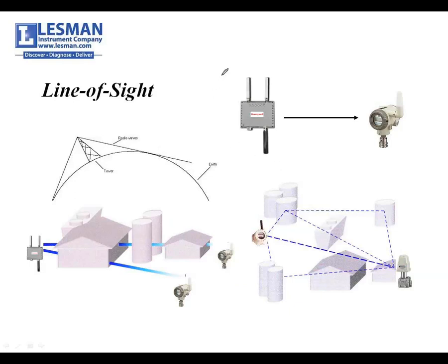In the industrial world, line of sight more typically means to us one antenna can see the other antenna. And again, 1,000 yards, antennas can see each other. This will work, no problem. We won't even have to come out and try it. Now, when you get down here, where we're going through things and bouncing off things, often we will bring gear out just to make sure that we can achieve and maintain good connectivity. Because at the end of the day, this thing's got to work and work well and be robust and have enough extra strength, especially in these outside environments, to shoot through the weather.